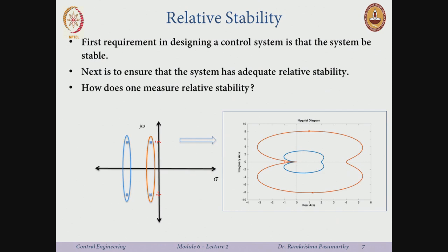Okay. So, how does the Nyquist thing now look? Here I just cannot directly measure relative stability. I can say, well, this is further from the origin, so it will still be safe if there are some changes in parameters or things like that. It might just come slightly to the right, or maybe even move to the left, and so on. But I can say that this looks a little more hopeful, the blue line, than the brownish one. This is paired poles.